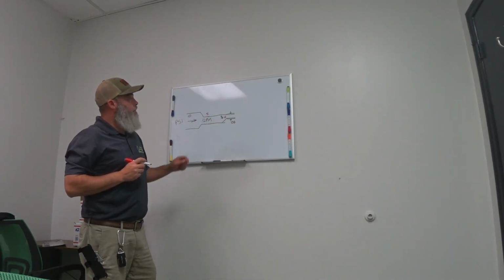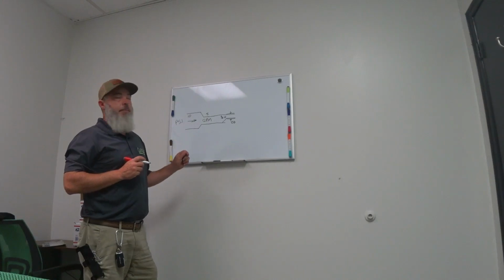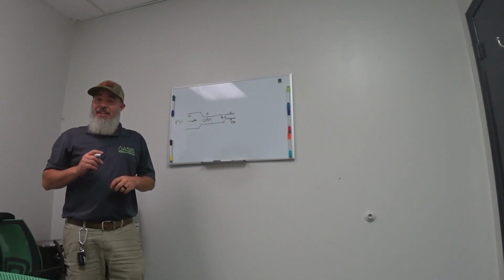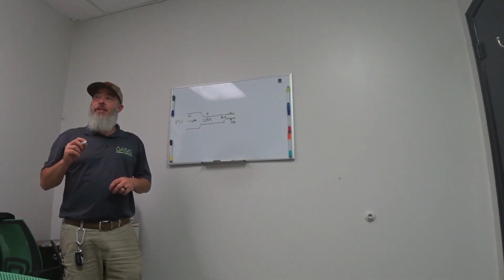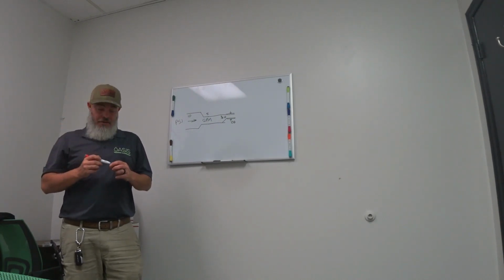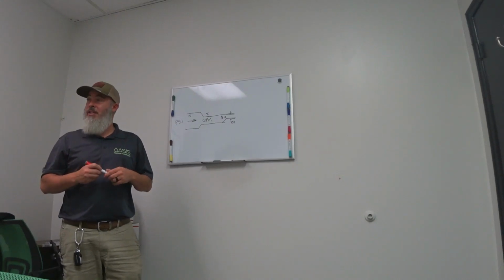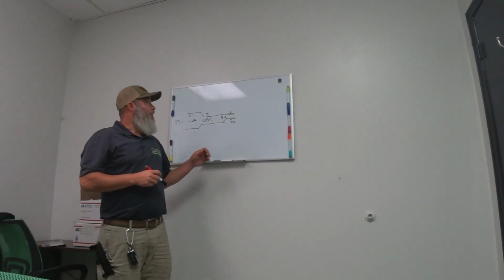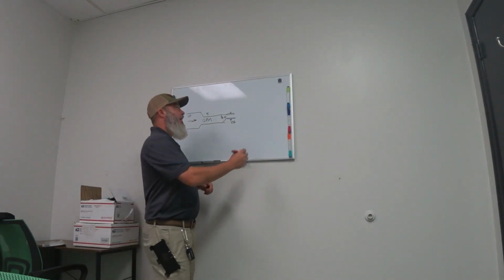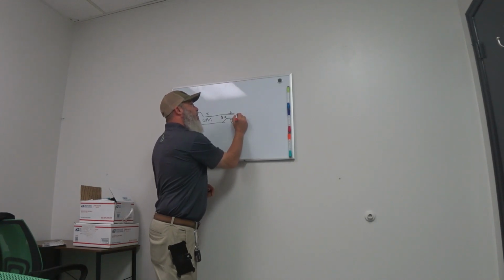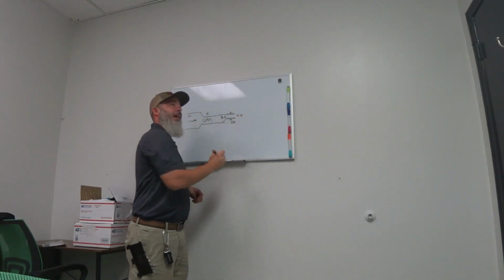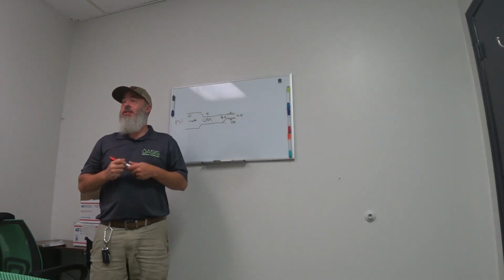And a lot of people use 3/8 copper. But if you use 3/8 copper, 3/8 is actually the measurement of the outside diameter, because that's how plumbers measure it. But if it's 3/8 outside diameter, it's only 1/4 inch inside diameter. And that is very small.